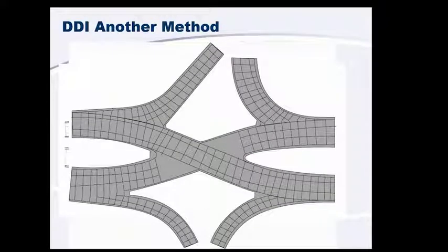There is also something that's being tried. I believe this is being tried in Wisconsin, and please excuse my crude drawing. I haven't had a chance to perfect this one yet, but this is similar to the pave-through method for roundabouts. You can see here one direction we choose paves all the way through, and then we would isolate this section so these approaches don't impact that central section. And I haven't had a chance to deal with the odd-shaped panels that are going to come up in here, but you can see how that may be another way you want to approach this.